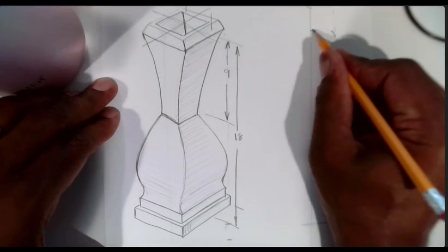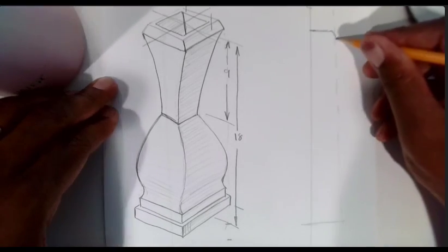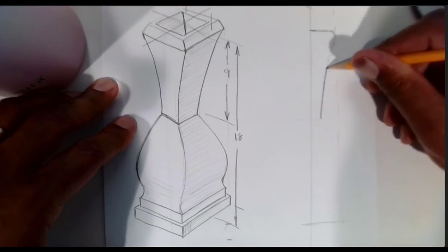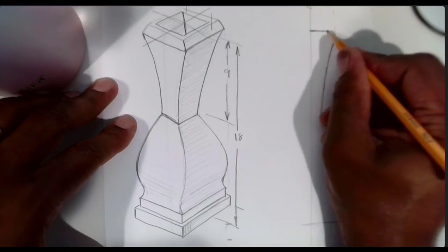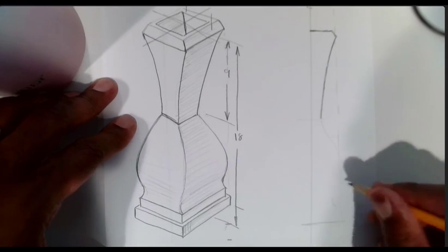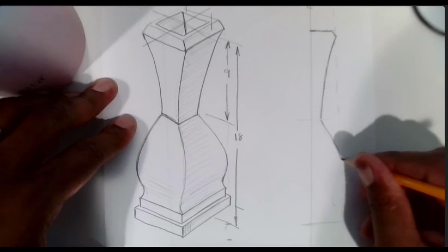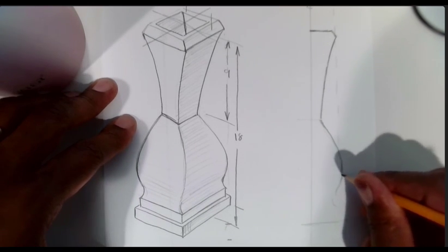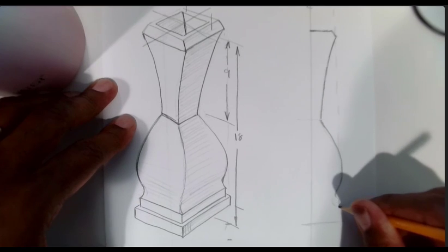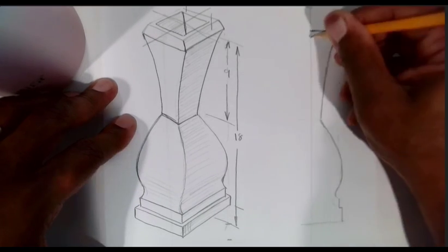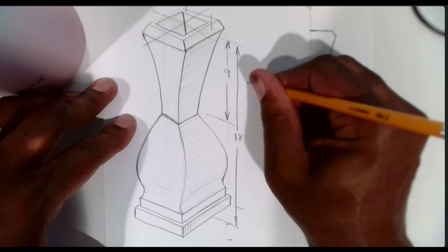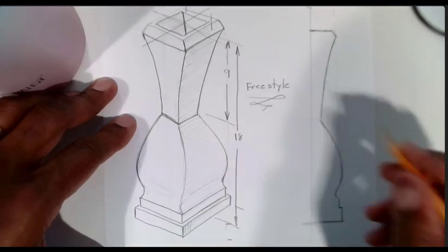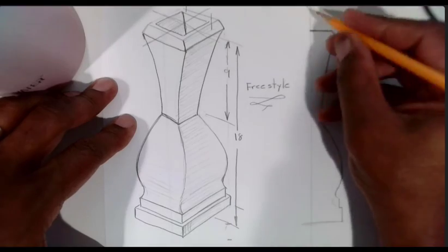Once I've got it in 3D, it gives me a really good feel for what I need to do in 2D. Of course, I'm only drawing one half of the profile anyway. This is the actual profile that's going to control the shape of the 3D solid model. I can mirror this, so there's no sense in drawing two halves of it.